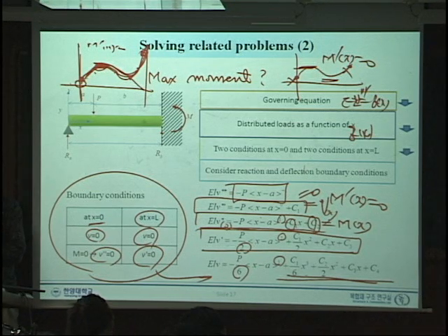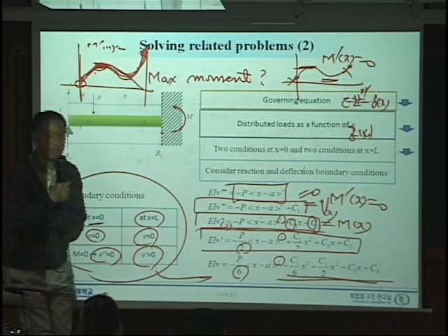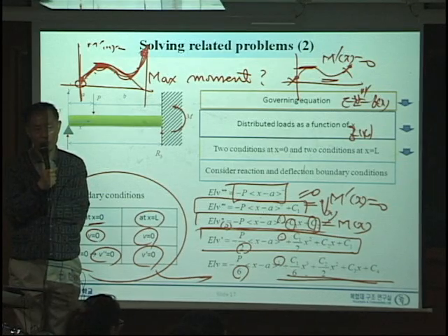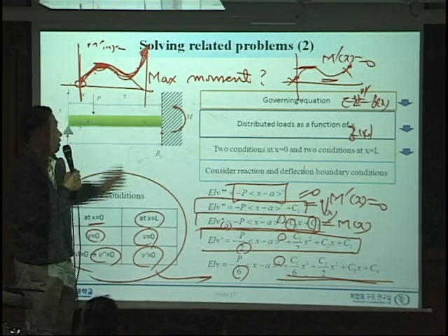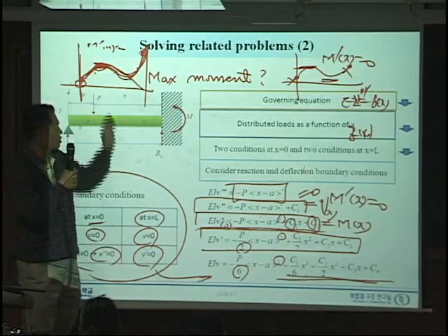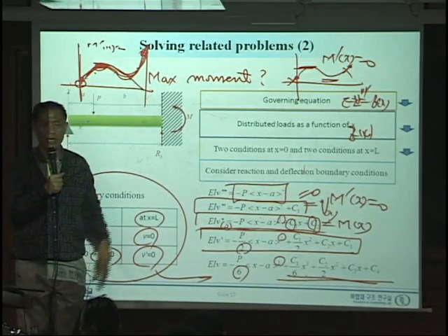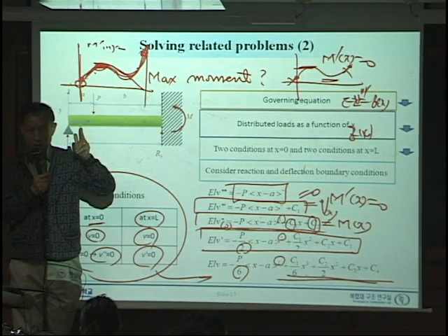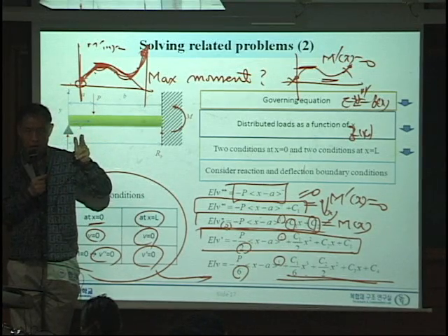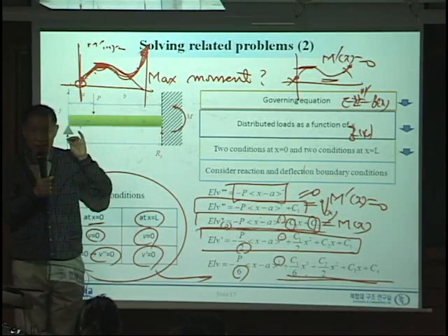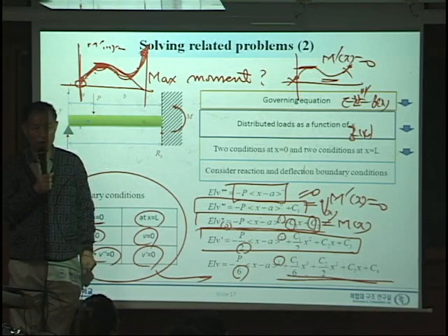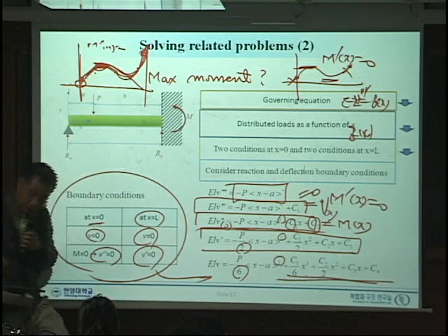The maximum moment is really important, because why is it important to get to know the maximum moment? Because whenever you apply force, not just concentrated, any load you apply, the failure always will occur at the point where the maximum occurs. Okay? So finding that maximum location is very critical.